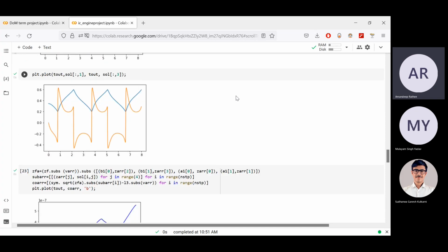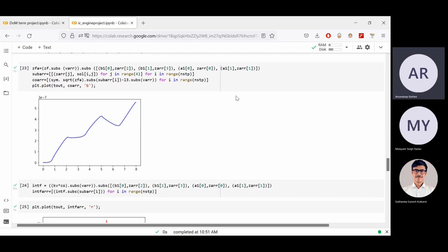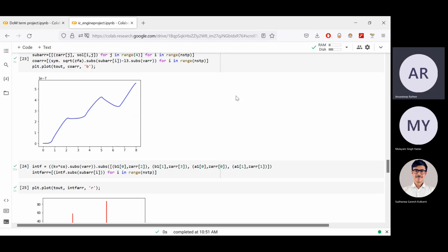After this mechanical analysis, we would like to find out what are the ground forces that are working. For the ground forces, what we have assumed is that we have apportioned the mass of the coupler on two parts. One is on the slider and one is on the end of the rocker that is moving through the 360-degree angle. I would like Sudhanwa to proceed with the slides to explain that part.